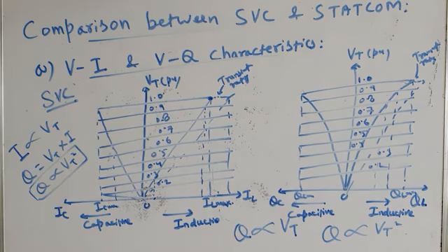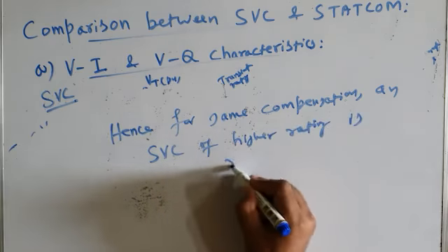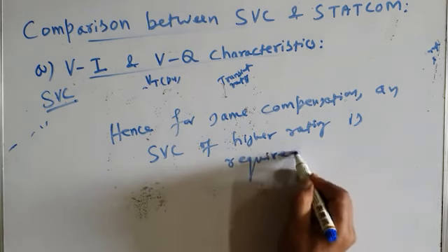Hence, we can say that for the same compensation, an SVC of higher rating is required. I will write this statement here. From these characteristics, we come to the conclusion that since STATCOM provides more effective compensation, for the same compensation, an SVC of higher rating is required. Or in other words, a STATCOM of lower rating is required.